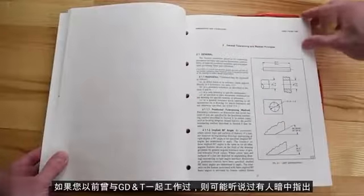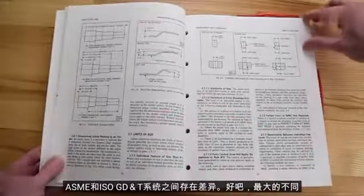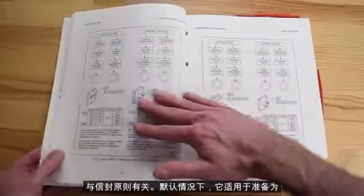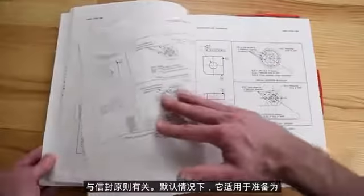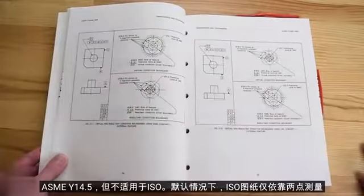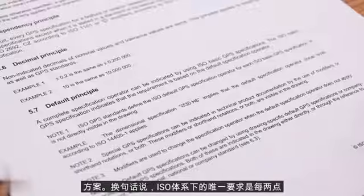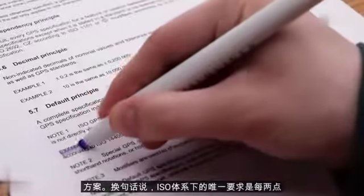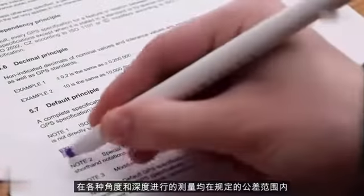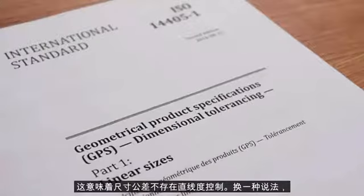If you've worked with GD&T before, you've probably heard somebody cryptically state that there are differences between the ASME and ISO GD&T systems. Well, the biggest difference has to do with the envelope principle. It applies by default on drawings prepared to ASME Y14.5, but not on ISO. ISO drawings, by default, rely only on the 2-point measurement scheme. In other words, the only requirement under the ISO system is that every 2-point measurement taken at a variety of angles and depths lie within the stated tolerance range. This means that there is no straightness control assumed by the size tolerance.